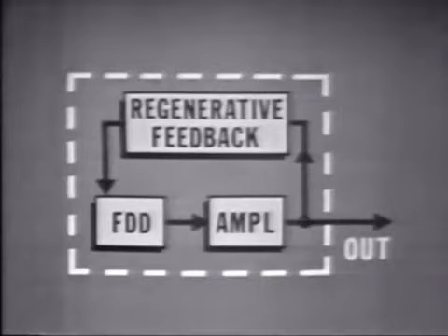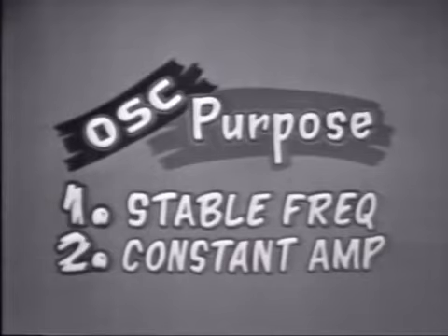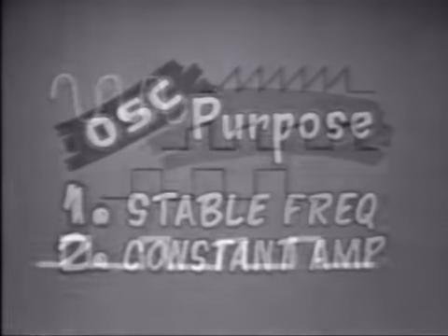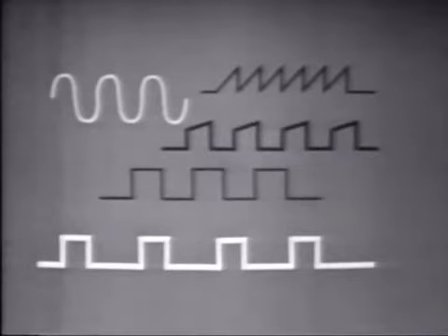However, there are several basic oscillator characteristics that are always true, whatever the type or application. First, any oscillator should develop a stable frequency and a signal of constant amplitude. Now, be sure you understand that this statement applies to all oscillators, the LC or any sine wave oscillator, as well as the sawtooth, square, rectangular, or trapezoidal oscillators. All of them should generate constant amplitude and frequency.